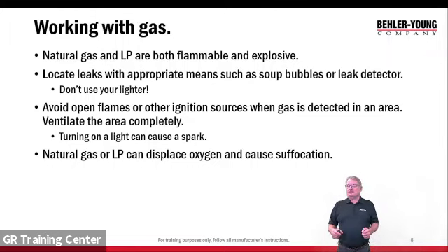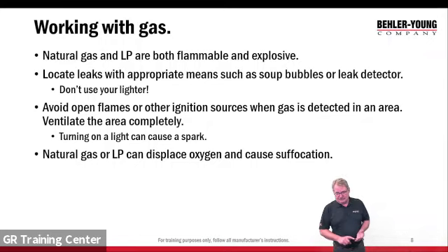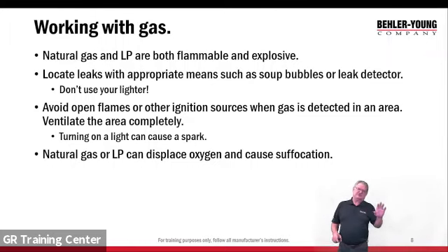So we want to use appropriate leak testing means. I've seen guys try to use their lighter to find a leak. That's obviously not the best way to find a leak. Use soap bubbles or appropriate gas detectors. If you have a large amount of gas in an area and you smell it, avoid open flames and avoid turning lights on. You want to open the windows and ventilate the area. Again, avoid any type of spark.